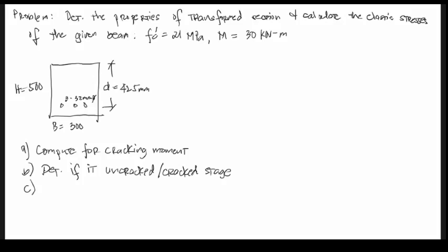Third, compute for X or the distance from the extreme compressive fiber to the NA, and compute also for the transformed section moment of inertia about the neutral axis. Then D, resolve for stresses. So these are basically our steps in this problem.